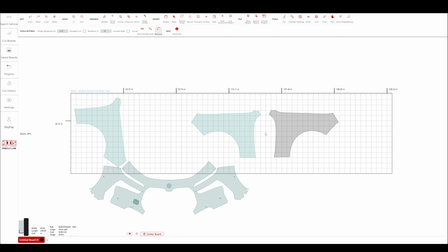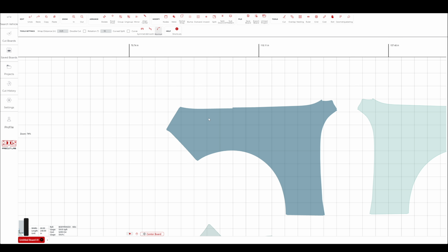So additionally, one of the other tools that we have at our disposal is our split tool. So say we want to be able to do just a partial fender. So let's go ahead with the pattern selected. We will use our split tool. Be careful not to use split down or up. We'll get to that one later. But in the modify section here, select that.